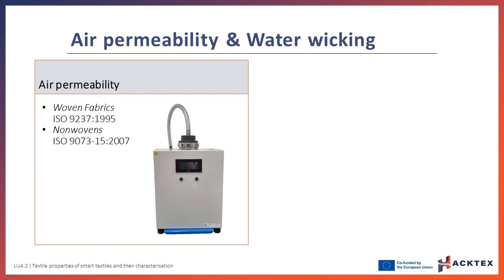The air permeability of the textiles is a very important property for those applications that need to control the amount of air that can pass through the fabric under certain conditions. The air permeability is understood to be the velocity of the airflow passing perpendicularly through the fabric, under the conditions of test surface, pressure drop, and time, specified by the standard.